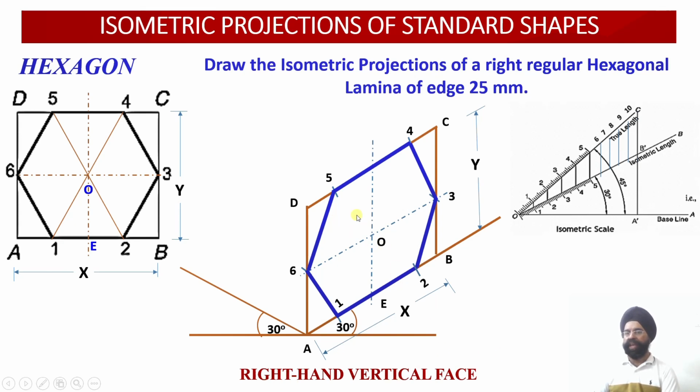If I have to draw a hexagonal prism, I will be extending the depth of the prism over here. Whatever is the depth given, the same depth I will be projecting along this particular side, and then this x-axis will be used over there.